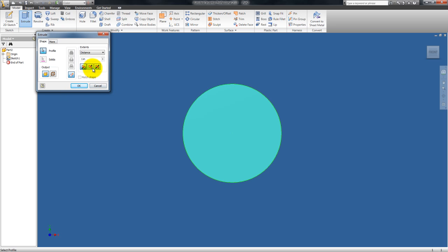So now this is the direction that we're going to be extruding in, so we can go out of the screen, into the screen, or in both directions equally. So then we want to pick the extent of the extrusion. So we can either go to another surface. So imagine in 3D if there's a surface closer to your face and we clicked that surface, then we could extrude this all the way to that.